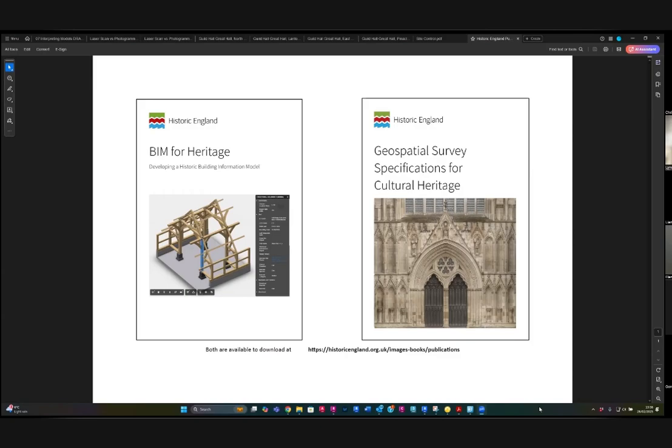I think the main thing to remember about accuracy is that it isn't just about the accuracy of the data that you collect and the project at the end. It's also about error control in between, making sure, for instance, like we spoke about today, that you're working from the same version, that you aren't working from a downsampled version, and that the downsampling hasn't stripped away some of the resolution and detail that you're relying on if you're doing, say, condition surveying with it. And vice versa. I think the QSs here will say there's got to be a real world check back, check measures and so on, just to make sure that things haven't diverged later on.